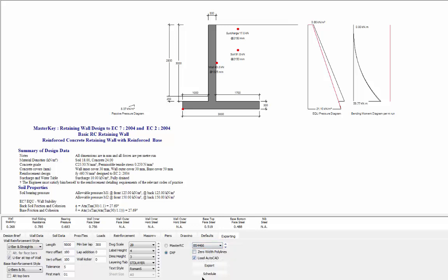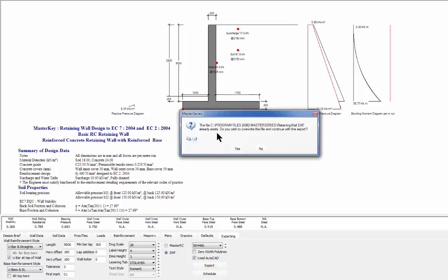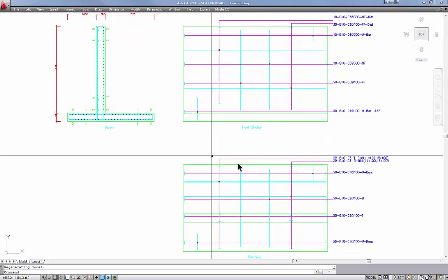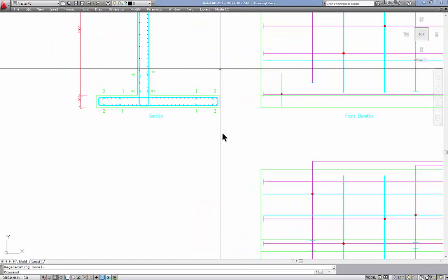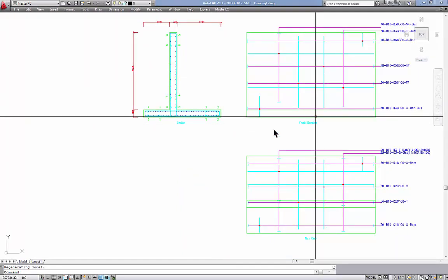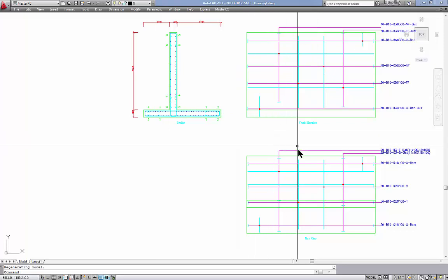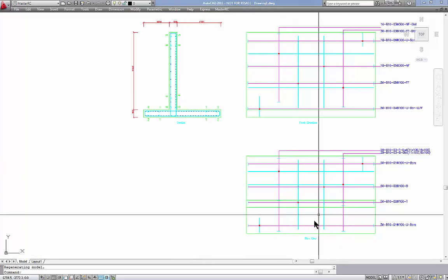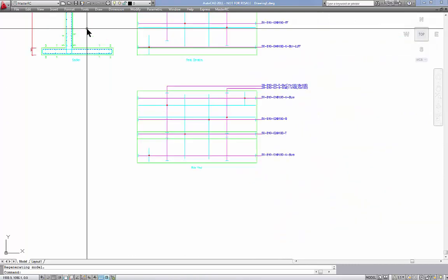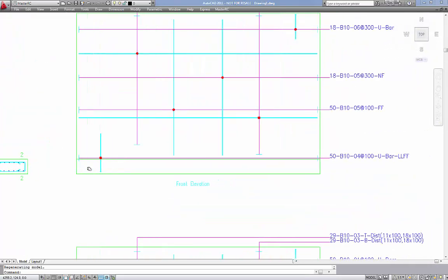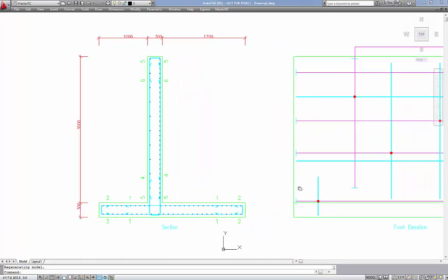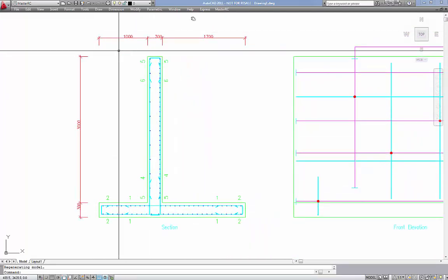And first of all, let's load AutoCAD. So let's export to AutoCAD. Yes, so there we are. There's my reinforcement and my front and back steel. As you can see, the overall length is going to be the 5 meters, so your bars are detailed out, and that's pretty straightforward and nice and clean. And there's your nice clean reinforcement with all your marks and your heights and your lengths.